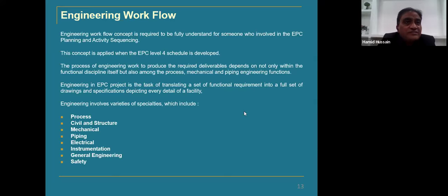And then, of course, electrical engineers will be doing the engineering, procurement, and construction phases, and they will be making the SLDs and MCCs, motor data sheets and motor controls, and the interaction with instrumentation for control from the DCS. And of course, instrumentation will take the P&IDs, and then they will start making the instrument index, IO list, and other deliverables like specifications for field instruments and other package instruments, and data sheets for pressure gauges, pressure transmitters, level transmitters, and all physical variable instruments.